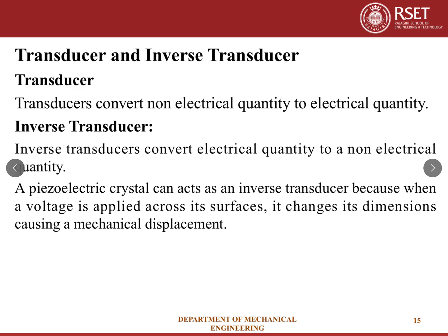The strain gauge is a passive transducer, which consists of a resistive element. When we apply stress, some elongation will happen in the resistive element of the strain gauge. As a result, resistance varies, and that will be measured as a change in the electrical signal.